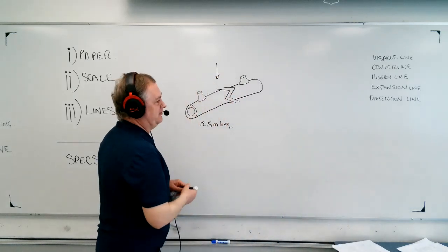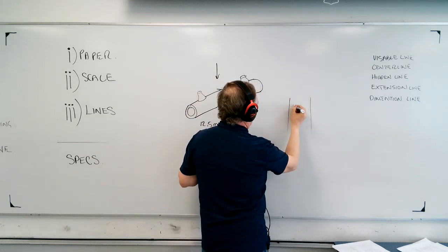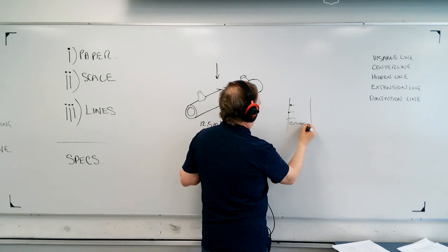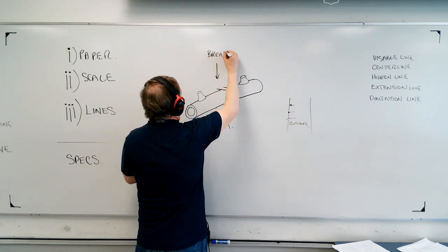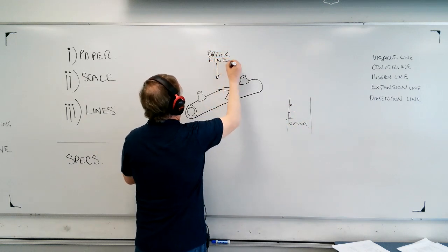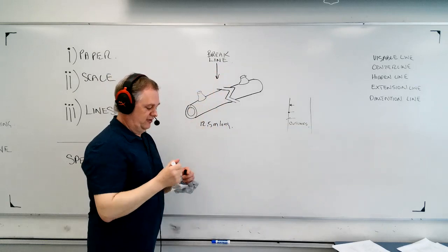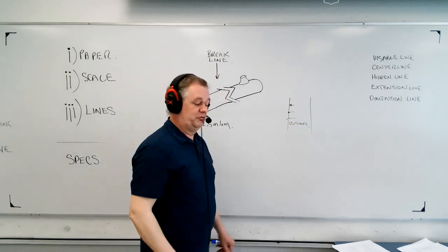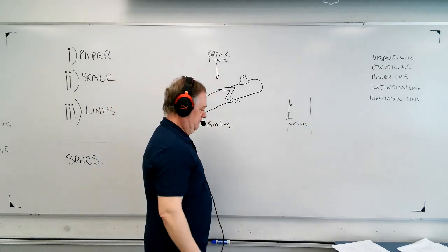Now they avoid using the word cut because cut line is the term that we used for whether we used an arrowhead cut line at the end of our dimension, or we used a dot, or we used a slash. Those were cut lines, okay? And so now, instead of saying cut line, we're going to say break. It's a break line. It shows a break in the material, so we're not going to see the whole thing. So these are very useful in conserving space on drawings when you can break away a piece that is just going to take a lot of space on your page. Okay, so break lines will cut away things that don't need to be shown.